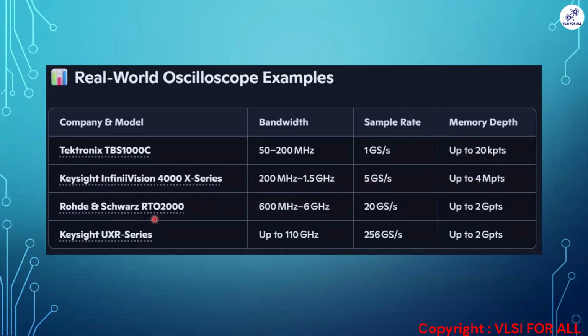R&S has 600 megahertz to 6 gigahertz, sampling of 20 giga samples per second, and memory depth of up to 2 Gpts. And Keysight goes up to 110 gigahertz, with a sampling rate of 256 giga samples per second and memory depth up to 2 gigapoints.